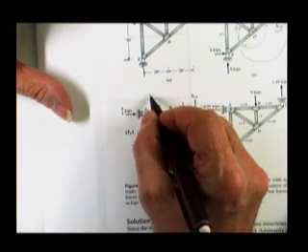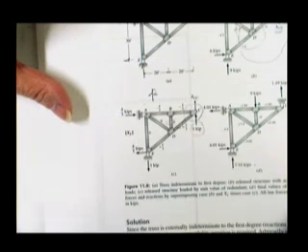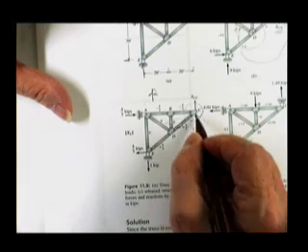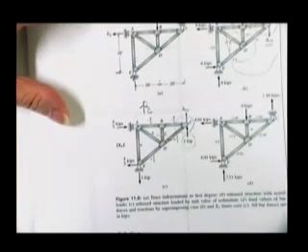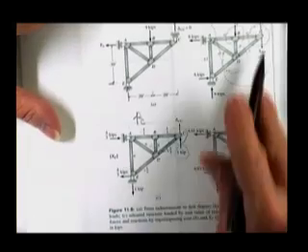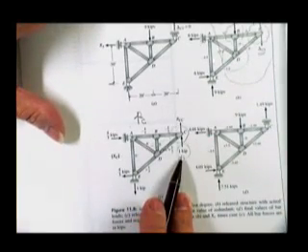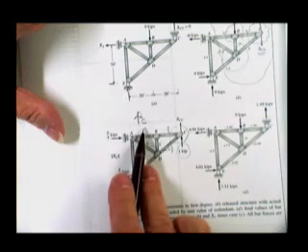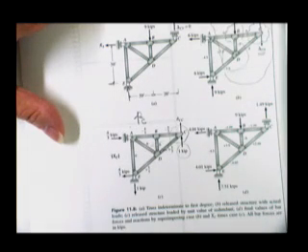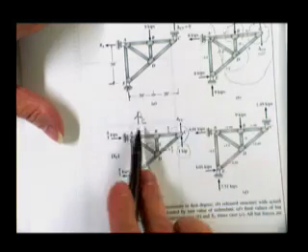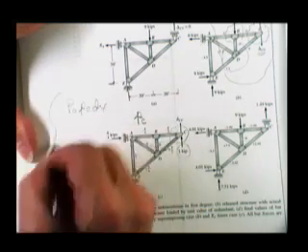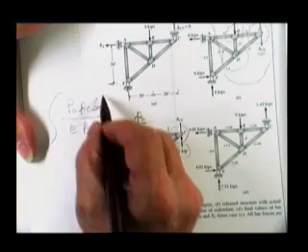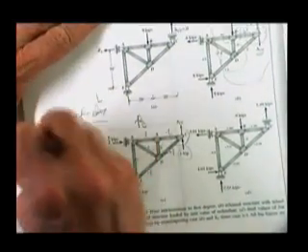So we'd call that, I don't know what we've been calling it, maybe lowercase p for a unit load at C. Then if you want to know the deflection at point C in this direction, you combine P0, PC, dx over EA, integrate across the length of the member, becomes P0, PC, dx, integral over EA. So that will be L once it's integrated.